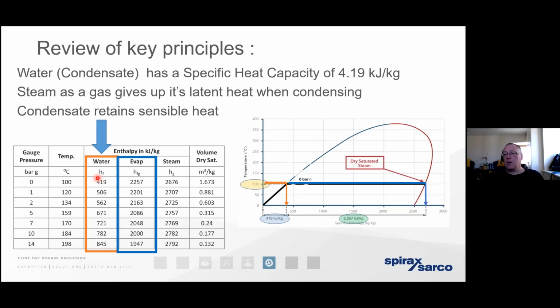A lot of condensate that's held back in the distribution pipework. Well, if we get fluctuating pressures, it means we're likely to get water hammer, that crash bang water hammer effect to the pipework itself. And any dry steam that is passing across a trapped mass of condensate is likely to degrade. So we're going to have a number of issues here by generating wet steam.